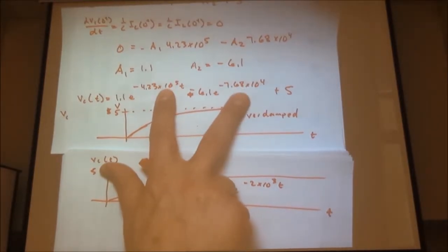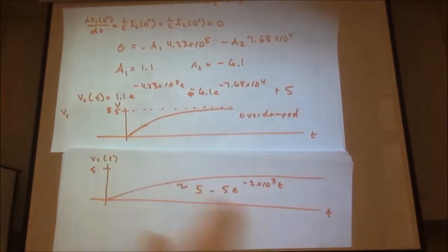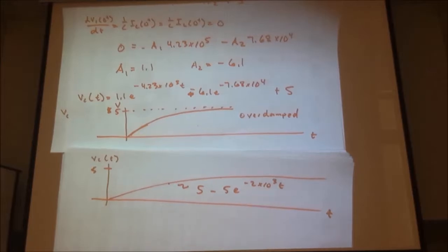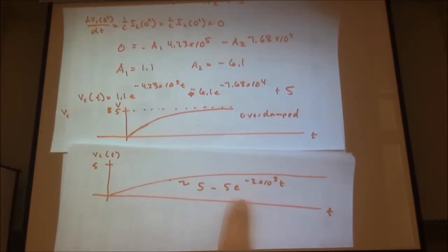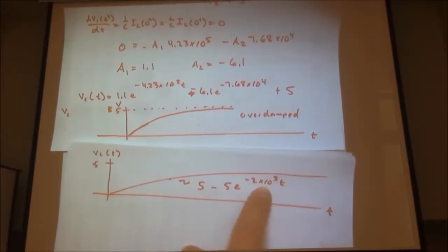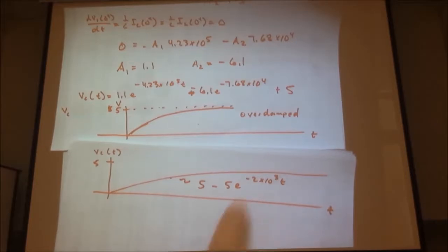So these S1 and S2 are much, much larger than this. This goes back to what we said physically early on. Our transient terms fade away more quickly as that resistor gets smaller. As the resistor gets larger, this term gets larger. As that resistor goes to infinity, well, we just go straight up to 5 volts. So that term becomes extremely large.